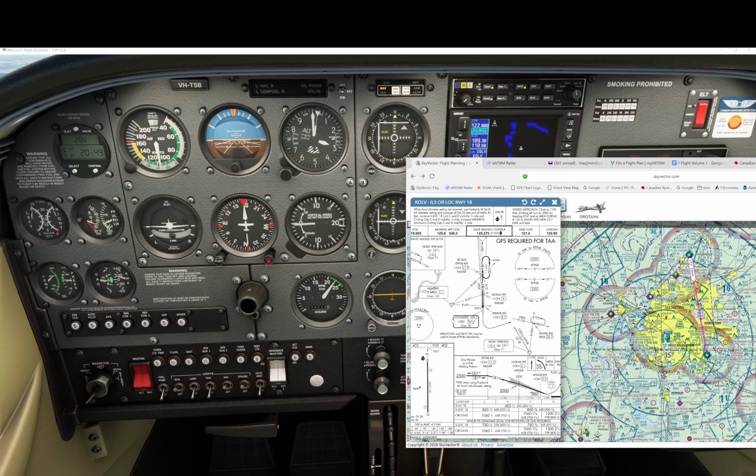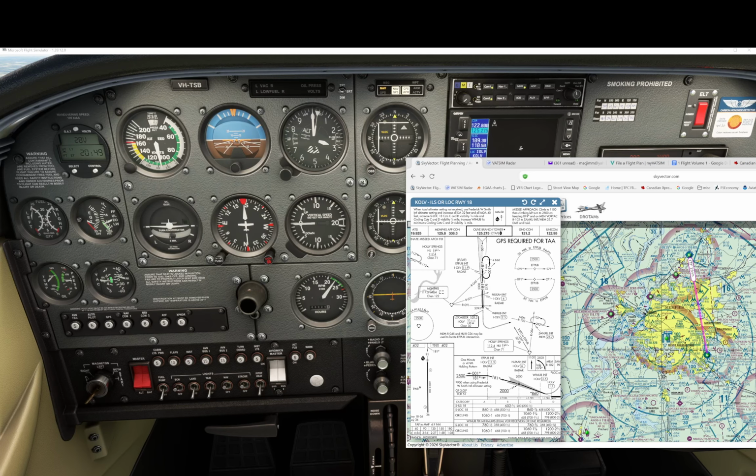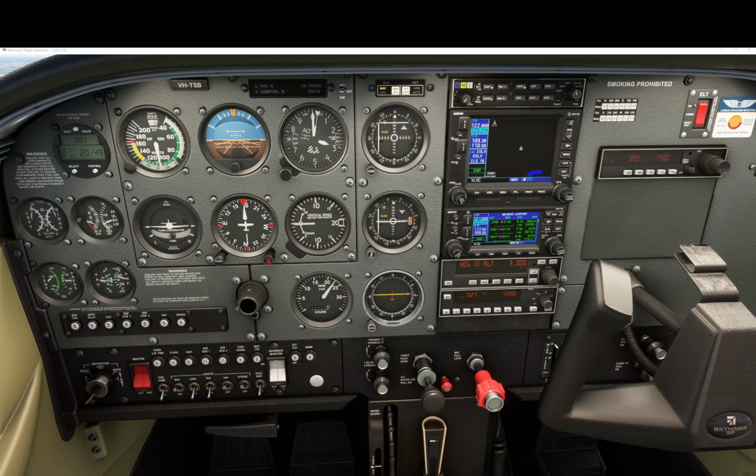It doesn't tell me how far it is from Memphis. So that's why I need GPS, because I have to determine when I'm 11.9 from Olive Branch. But I want to be on the radial 045, or I want to intercept radial 045.